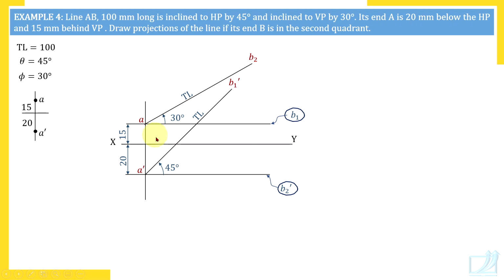Now, as good as we have solved the problem. A few more lines and rotation of EL or PL, and you will get the answer. So this is how these problems are very simple. What is the procedure after bringing all those dimensions on paper? Through labeled points, draw horizontal and vertical lines. And when we are sure that there are horizontal and vertical lines through all labeled points, then rotate EL or PL using a compass. So let's do that.